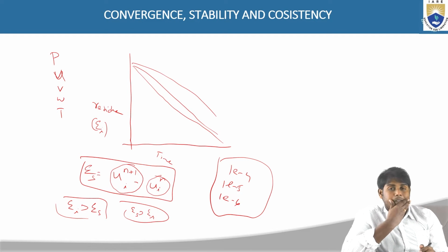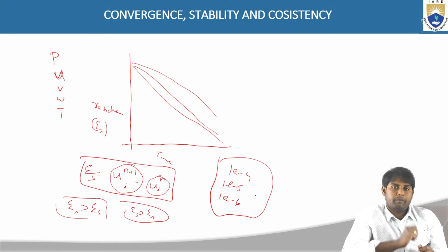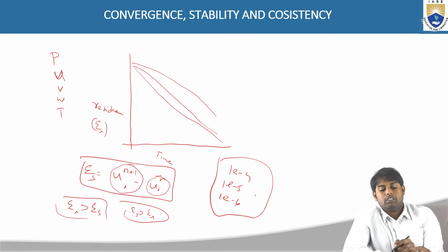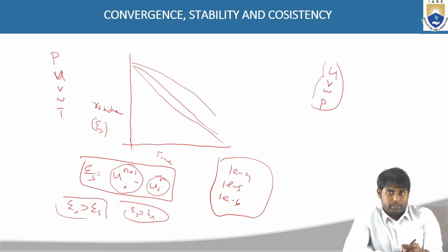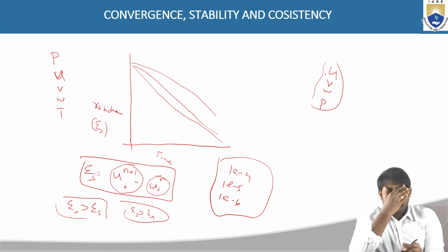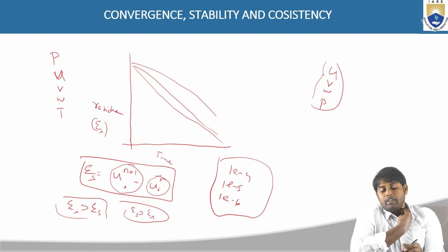Okay, so if we are having only incompressible flow with no heat transfer, the residues we observe are for u velocity, v velocity, w velocity, and pressure. In the sense, basically you will take the continuity and momentum equations. So it's continuity and momentum error. The residue will be for continuity and momentum.